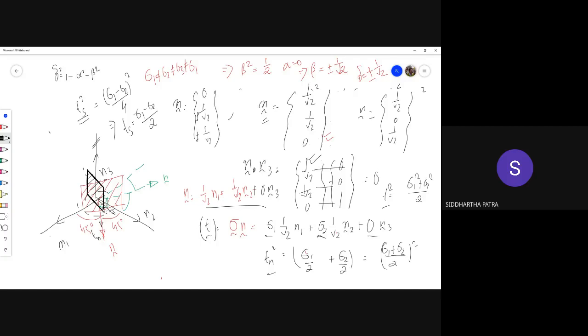Okay, so it would be lying on the n1 n2 plane. The traction itself along with the normal would lie on the n1 n2 plane, although the normal is perpendicular to a plane that is actually normal to the n1 n2 plane. Now this much is the shear component, right? So the direction would be normal to n on the n1 n2 plane.